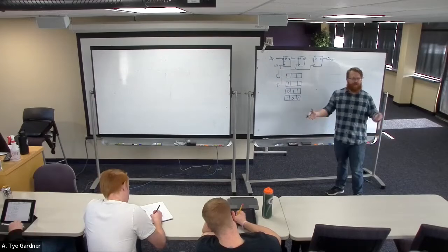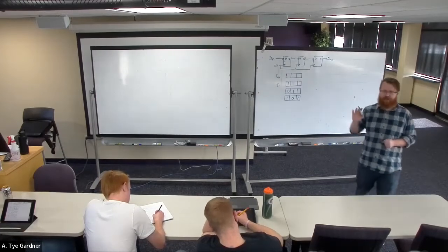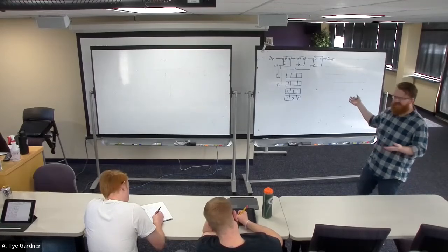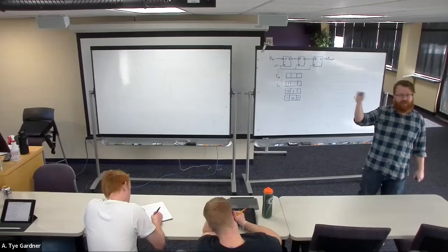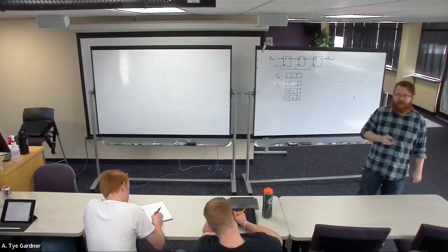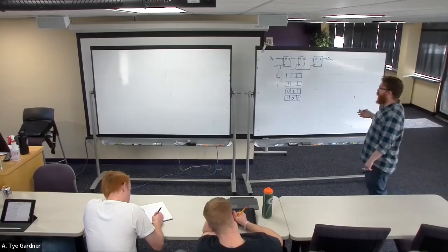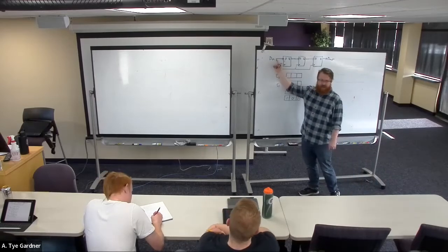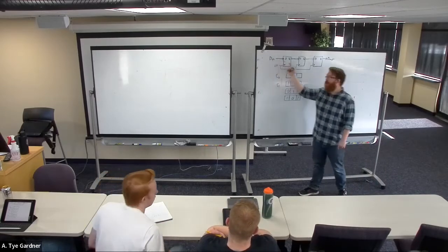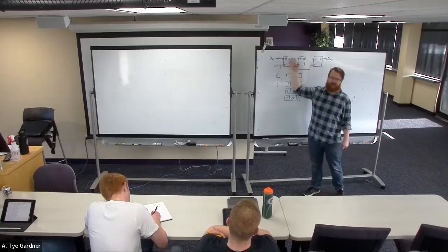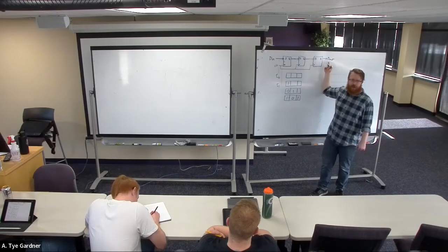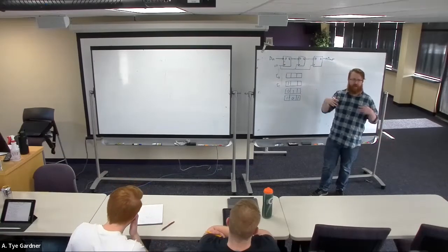Okay. This basic shift register, the simplest version that we have, functions as a queue, essentially. It can just create a queue of things. There are some issues with this one in order of queuing, which is if the data in is not valid, if whatever's coming in here isn't ready, but you need to shift the next one out, when you do that shift, you bring in invalid data, which then gets passed through, and you have to keep track that at this clock cycle of the output, we just throw that number away because it was bad. We had to bring in a bad one.